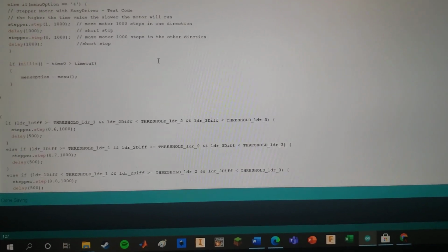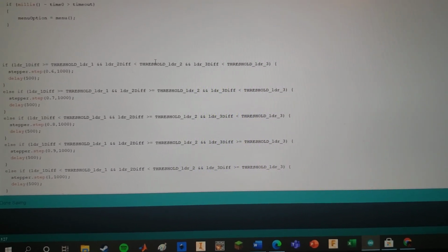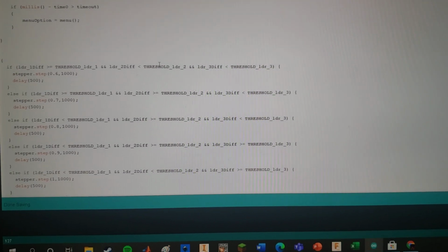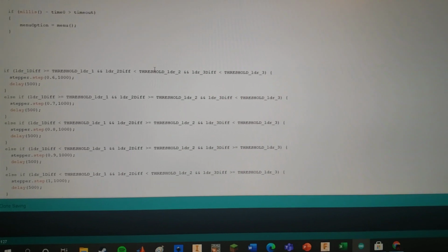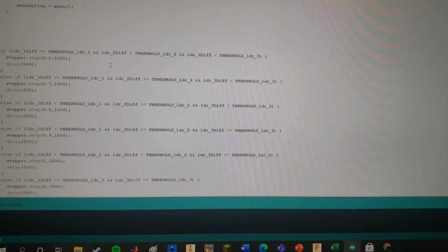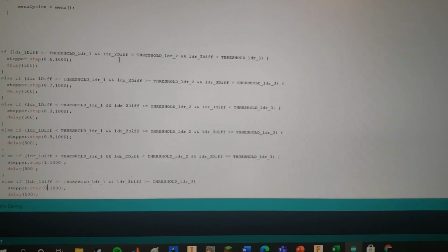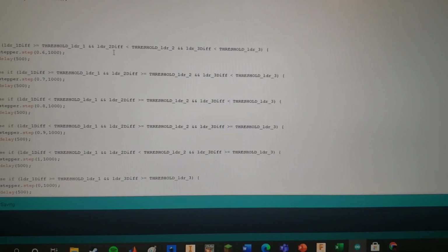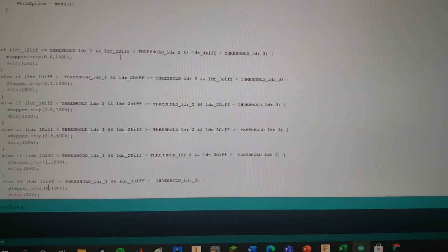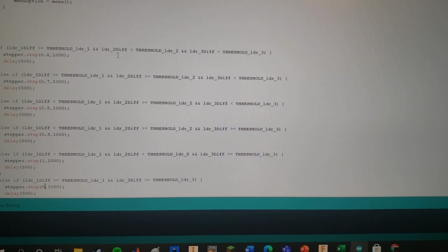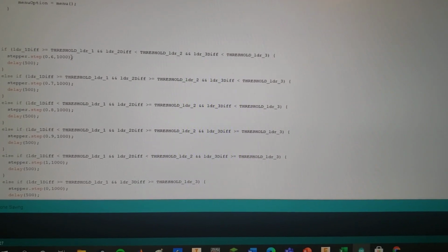So after I establish all of that, I then establish what outputs you get from the specific inputs. So, for instance, an input of just blocking the light that would be on the first photoreceptor or photoresistor would result in 20% speed for the motor.